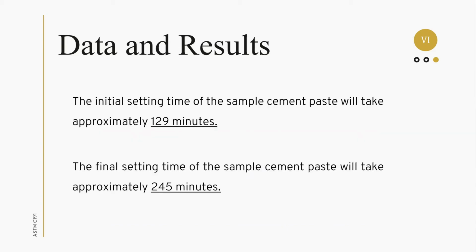Through the data that we have gathered, we have come up that the initial setting time of the sample cement paste will take approximately 129 minutes, and the final setting time of the sample cement paste will take approximately 245 minutes.